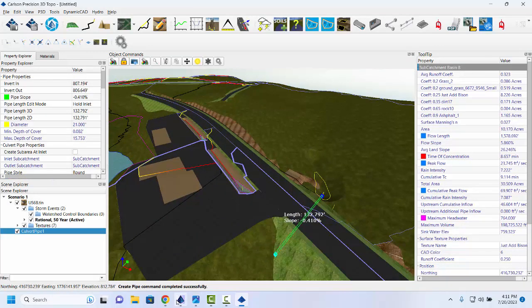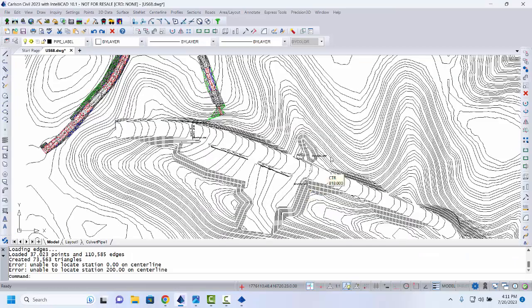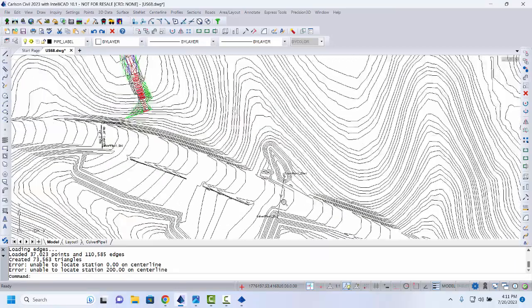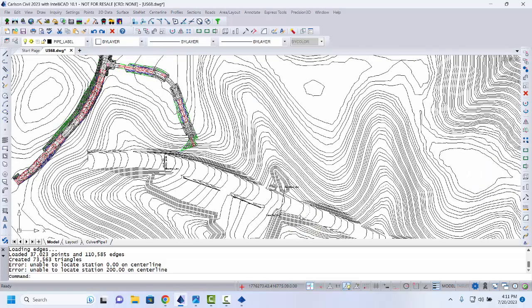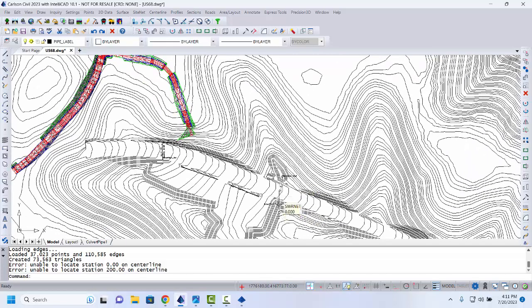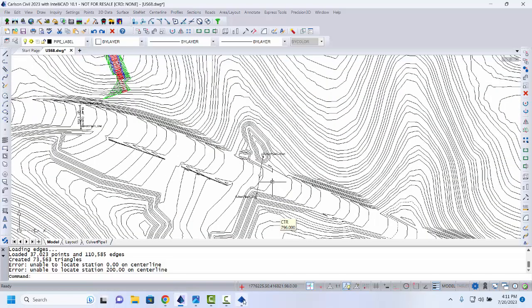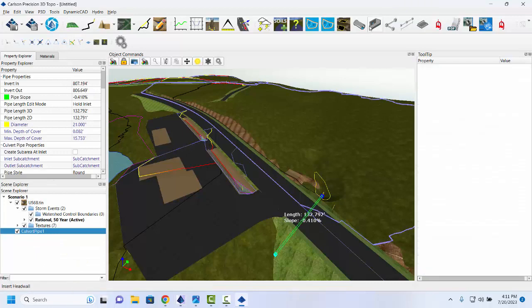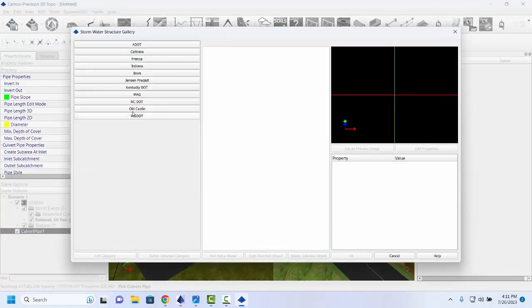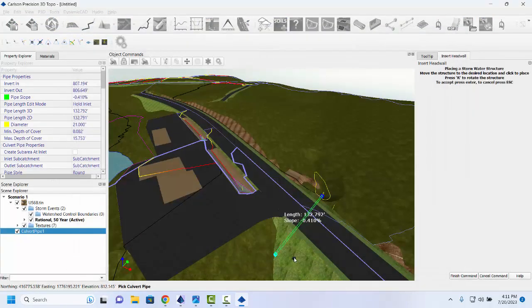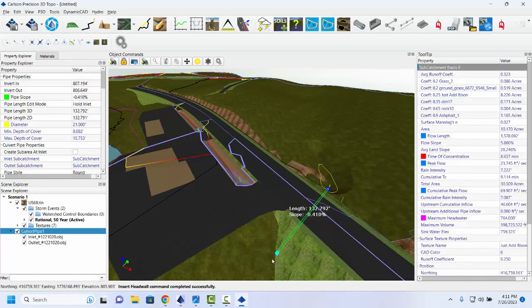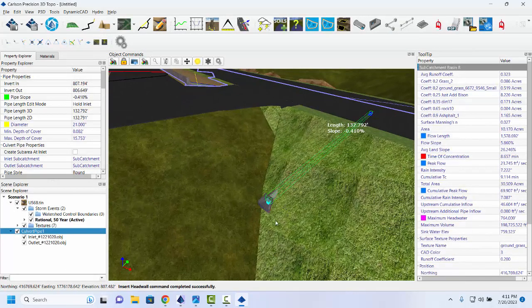And if you go back to the CAD, that culvert is drawn. It's drawn across, and if you set it up to draw both sides of the pipe, you'll actually get two parallel lines. Right now we're just set up for one. Going back to the CAD, if you use the headwall feature and drop in, say, an old castle headwall on the end of the pipe, and finish the command, you'll see that we have the head wall located.